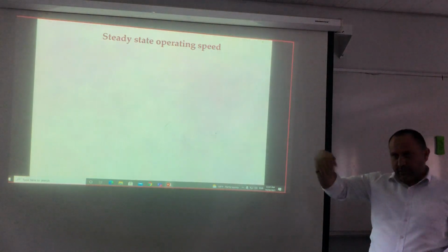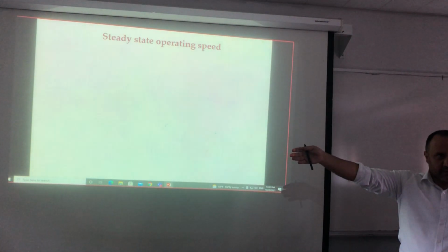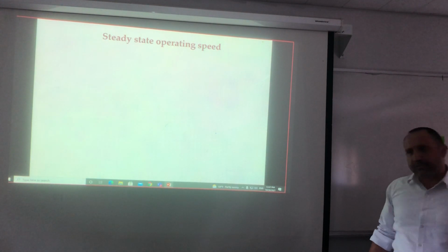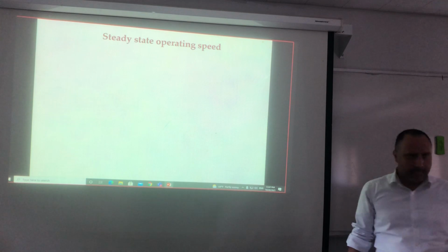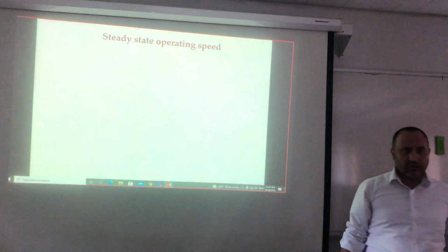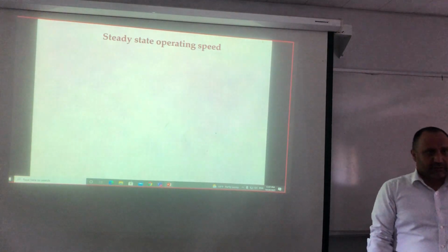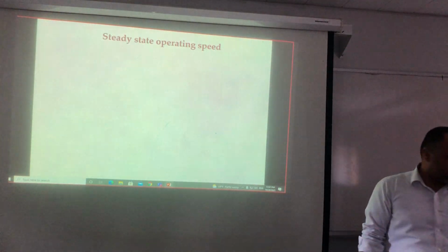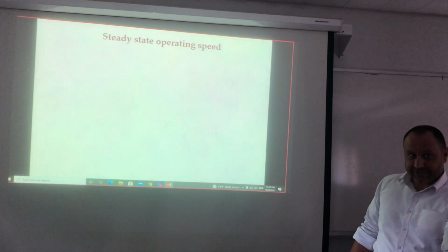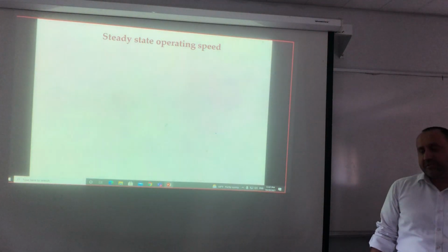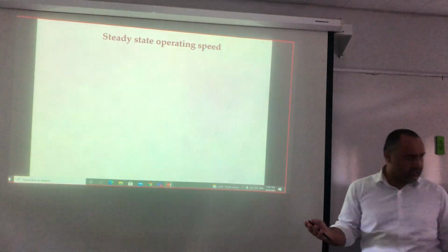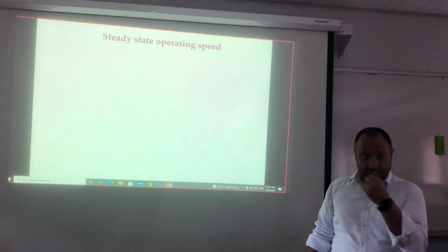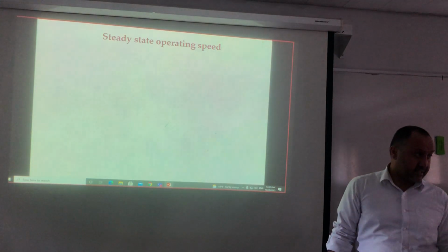When any d by dt goes to 0. According to the transient response characteristic, it is 5 times the time constant according to the 5% criteria, or 3 times the time constant if 2% criteria. But simply, because you know that 5% is okay. Do you know why they make this definition of steady state?